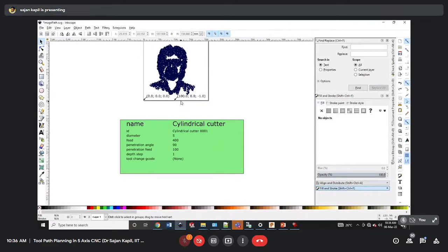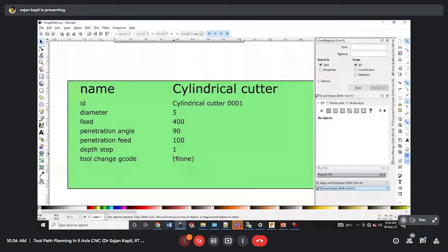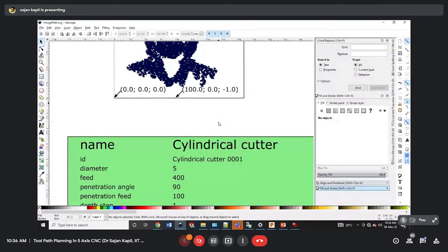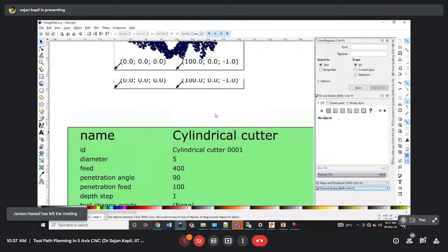On the same plane, it is going to remain as you are seeing in the toolpath we have generated. But as you are seeing, we have to deposit several layers. That you can change here. Depth is step. Right now, it is reaching a depth of minus 1 mm in a single step. You do one thing: here, instead of -1, you type for example 10, and each layer is 1 mm. Then it will create 10 layers.